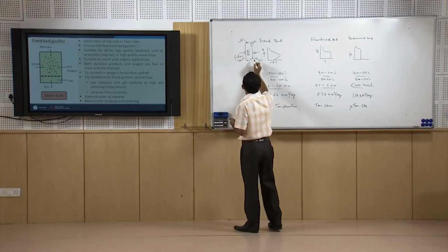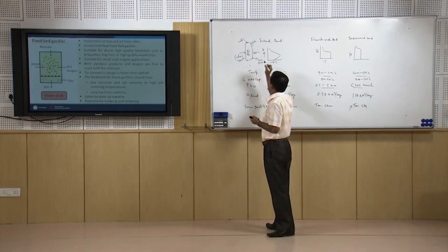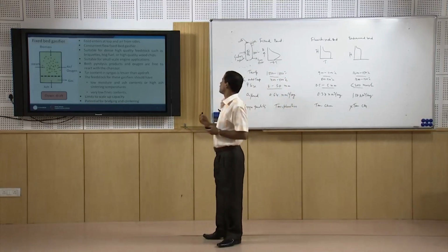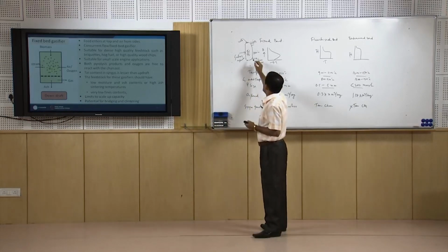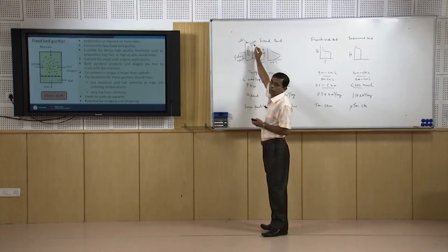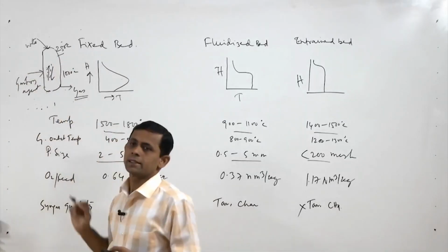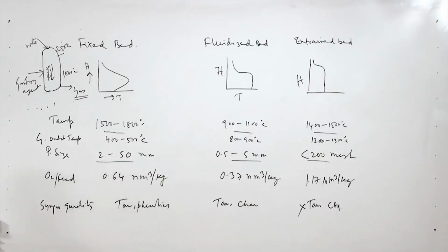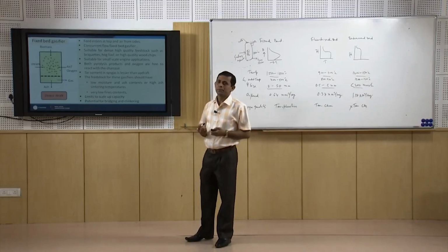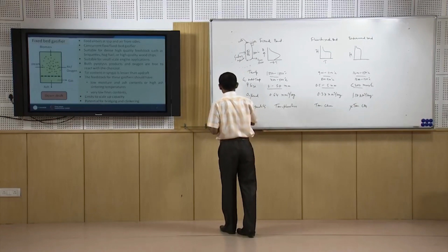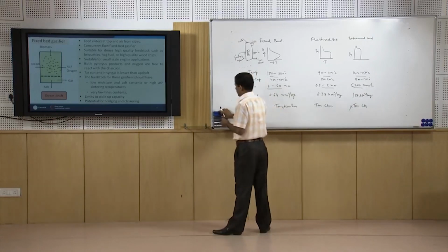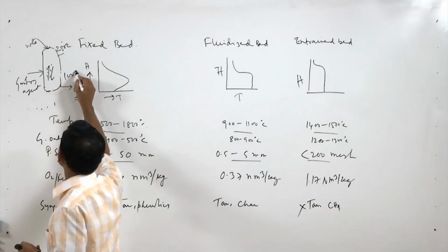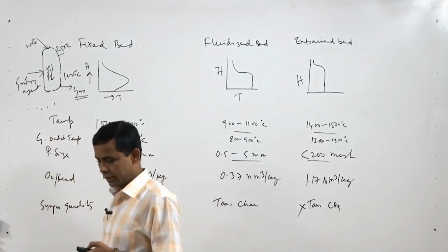That is why the syngas is of better quality than that of the updraft gasifier, and as the temperature is also higher than 250 degree centigrade, the tar content is less here. But the disadvantage of this gasifier type is the scale up problem. This gasifier has some scale up problem. The temperature inside this is around say 1000 degree centigrade, again 1000 degree centigrade.